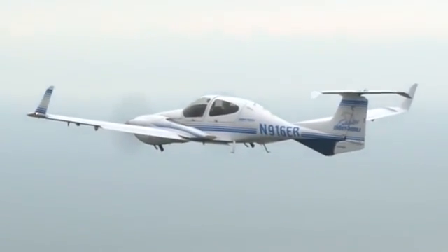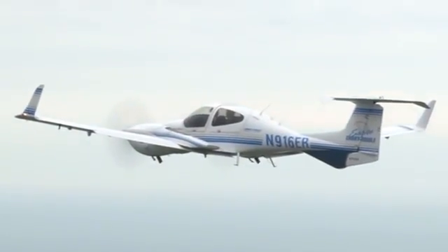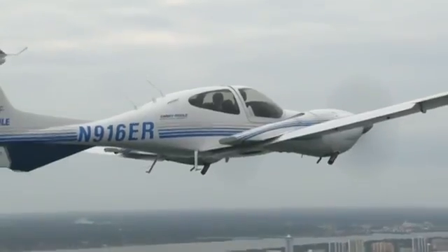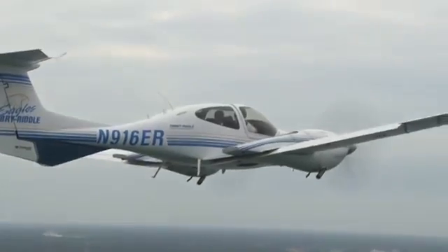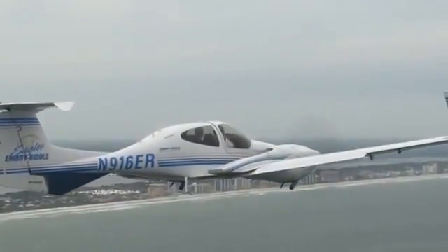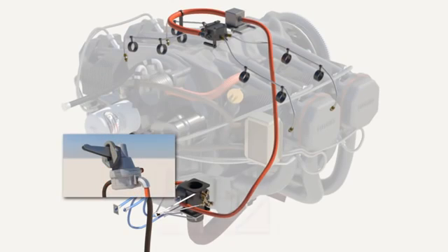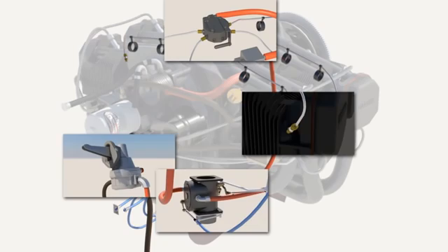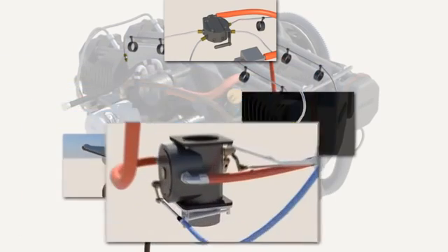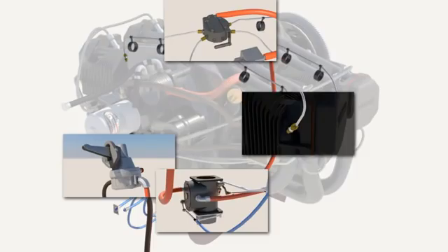In newer airplanes, fuel injection systems are installed, which have many benefits over carbureted engines. Fuel injection engines reduce the amount of fuel required, increase engine power output, and allow for the precise use of the fuel. Rather than having a carburetor, a fuel-injected system is split up into different components. These consist of fuel pumps, a fuel control unit, a fuel manifold valve, and finally, fuel discharge nozzles.